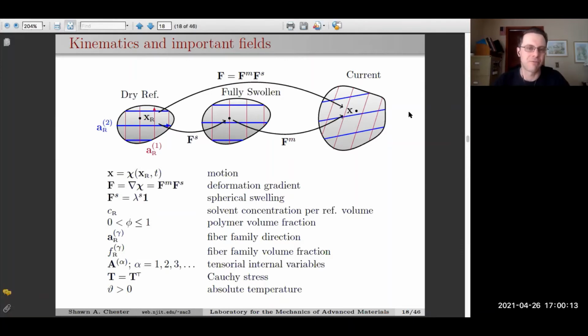and mechanical deformation. The swelling, you could say, is, we had this sample, for example, we put it in a jar of toluene, close the lid, came back in a day. There, it's just the volume change, essentially, just swelling. Then we could take that sample, go over to the testing machine, go to the Instron, and do a tension test on it. So that's one of the reasons why we have this breakdown for mechanical and swelling components.